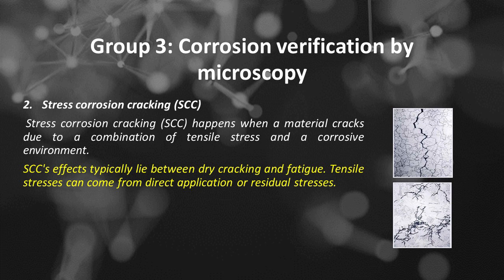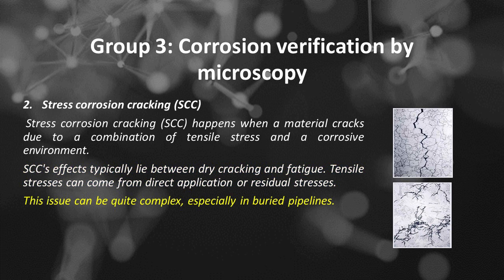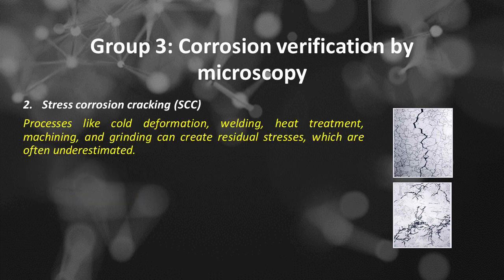SCC's effects typically lie between dry cracking and fatigue. Tensile stresses can come from direct application or residual stresses. This issue can be quite complex, especially in buried pipelines. Processes like cold deformation, welding, heat treatment, machining, and grinding can create residual stresses, which are often underestimated.